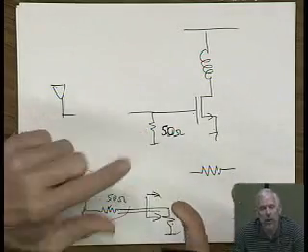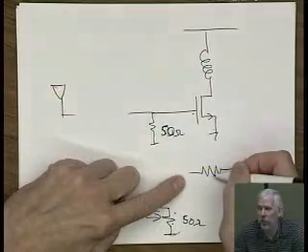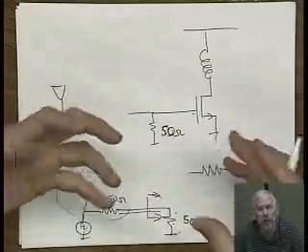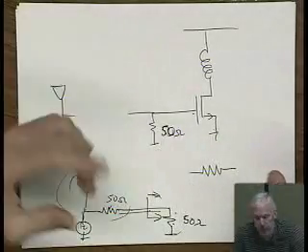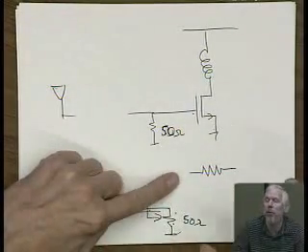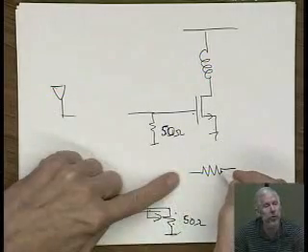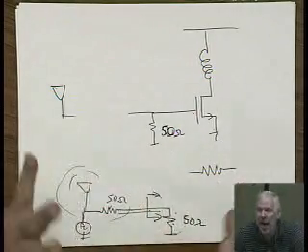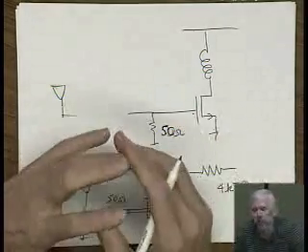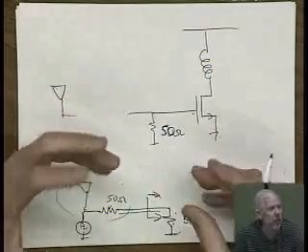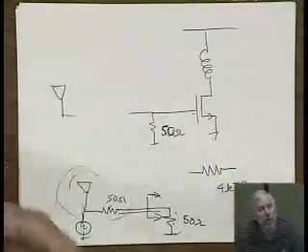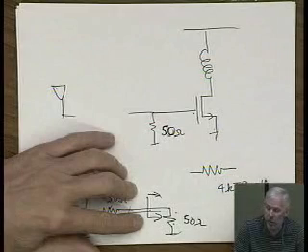It's thermal noise. Once you have a resistance, you actually have random fluctuations. This is very low-level thermodynamics. There's just no way to get around this. The amount of noise in a resistor works out from very fundamental thermodynamic arguments. This has nothing to do with good resistors and bad resistors. A pure resistance has to have a noise of 4kTR. It almost comes from entropy. As soon as you have a loss like this, you've got to have some randomness, and randomness is noise.